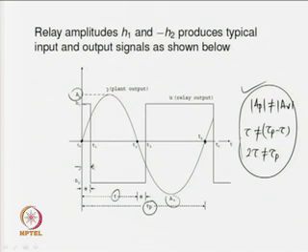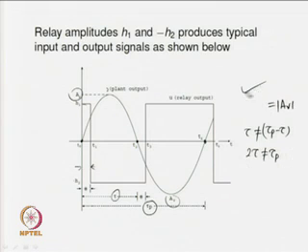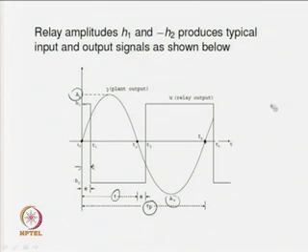These are happening because we are employing an asymmetrical relay during the relay test. So, the relay test is initiated such that one obtains an asymmetrical, sustained oscillatory output from the system, and it enables one to make a few more measurements than 2 measurements. So, what are the measurements one has to take from this output signal? Those are the peak amplitude A p, another peak amplitude given by A v, the half period tau, and the full period tau p.